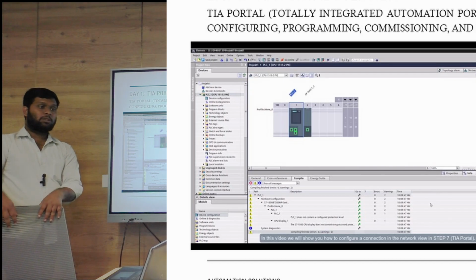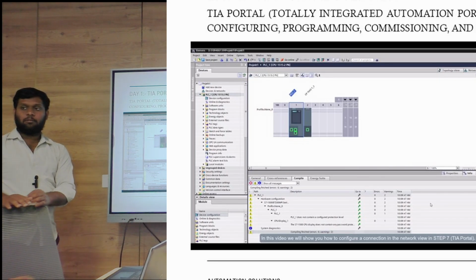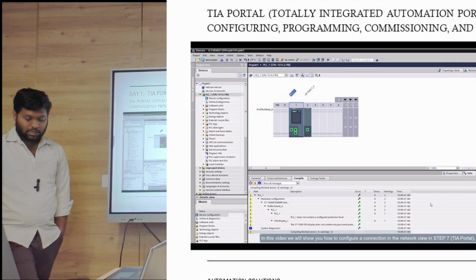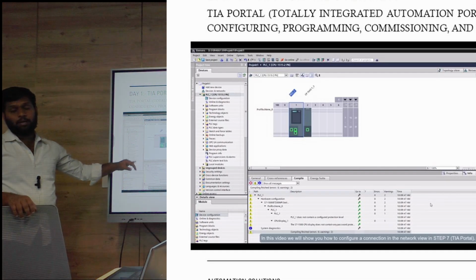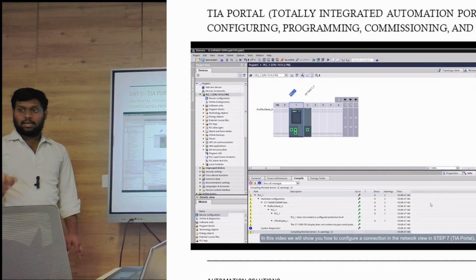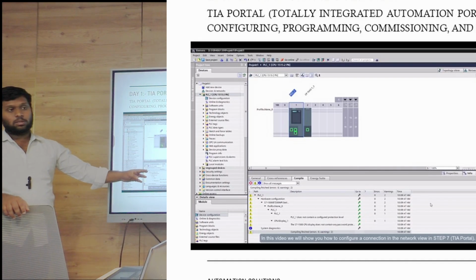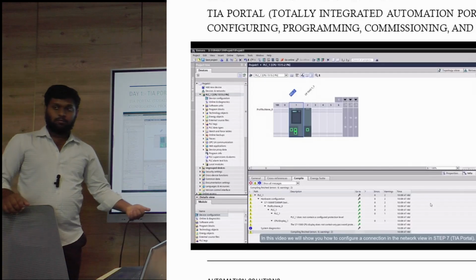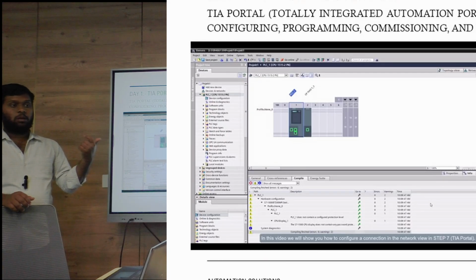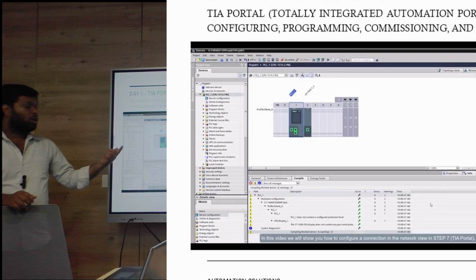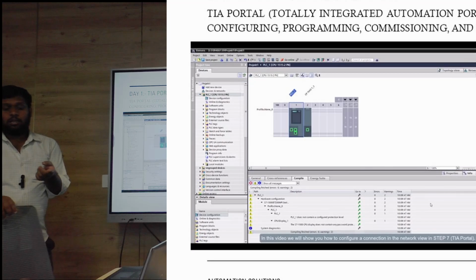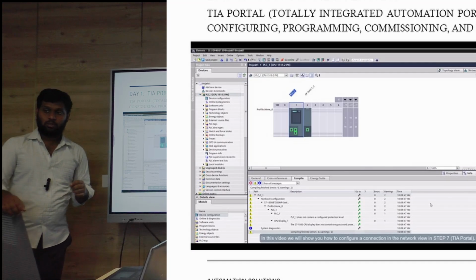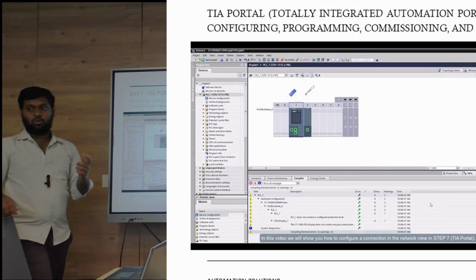Suppose we don't have any provision to act on that push button; simply, in the force table, we can add the tag name or tag address, and it will give us the status of the tag and how to force it. We will show that by forcing that input. Visually the PLC sees that the card has got 24 volts, so it will be triggered from 0 to 1.